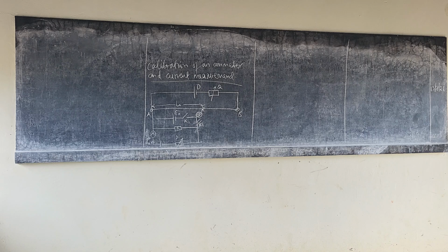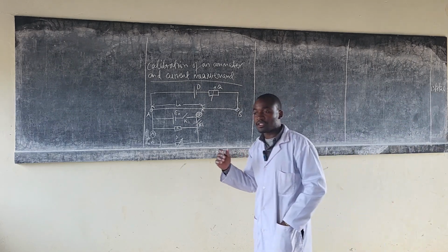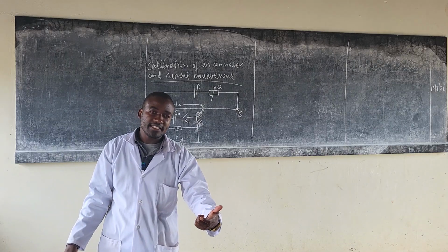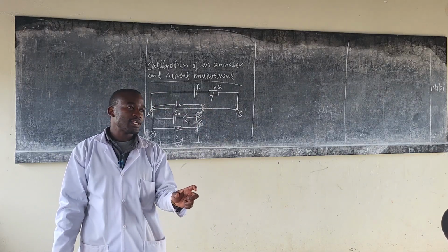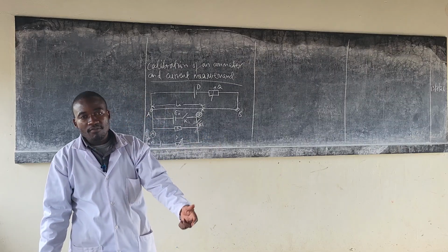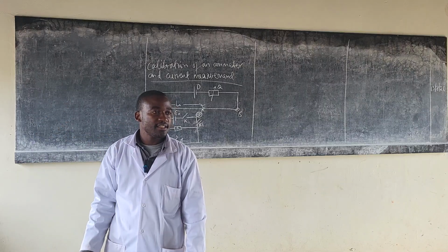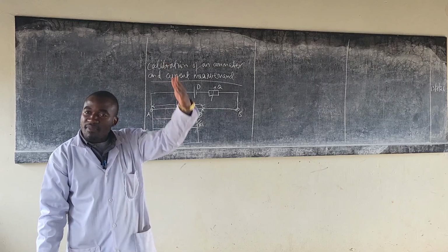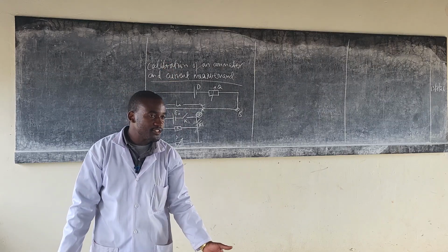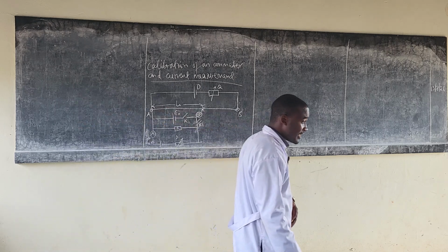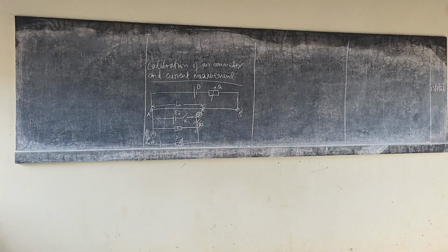In your heat and thermodynamics, you looked at how to calibrate a thermometer, whereby you place it into an environment that looks like ice. It gives you a reading, you mark the point. Then you get the same bulb, and after shaking it vigorously, you put it into steam. Again, the thread rises. You mark the point. Measure the distance, divide it by 100. You will have calibrated the thermometer in degrees Celsius. So basically, calibration is an English terminology used to mean giving a scale to something.